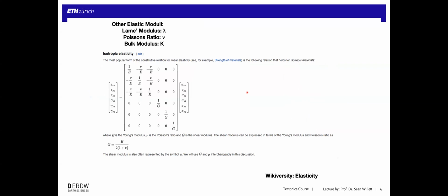If you look at the full 3-dimensional problem of elasticity, we have to worry about, and I hope you've seen this before, that in a 3-dimensional body, there are in fact 6 independent components of stress. So there are the 3 normal components, XX, YY, and ZZ, and then we have the shear components, YZ, ZX, and XY. In fact, there's really 9 components, but because of symmetry, 3 of those disappear, and we have 6 independent components. And the same is true for strain. We have to worry about those as well.